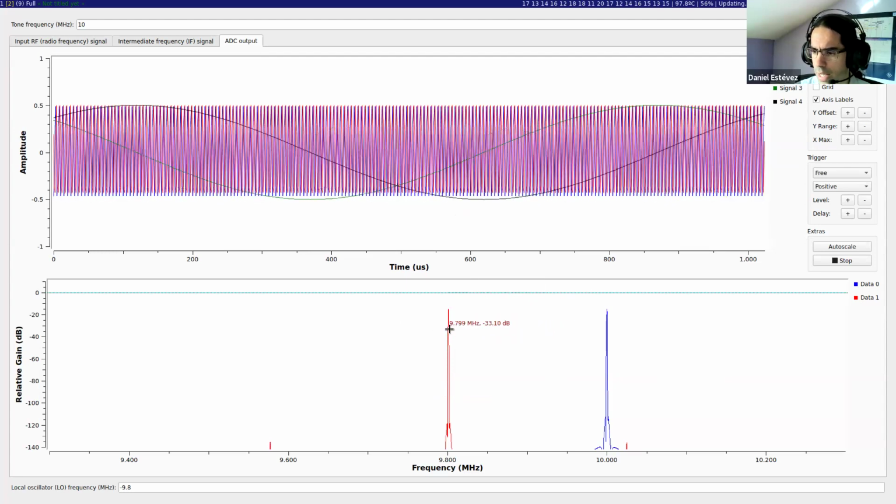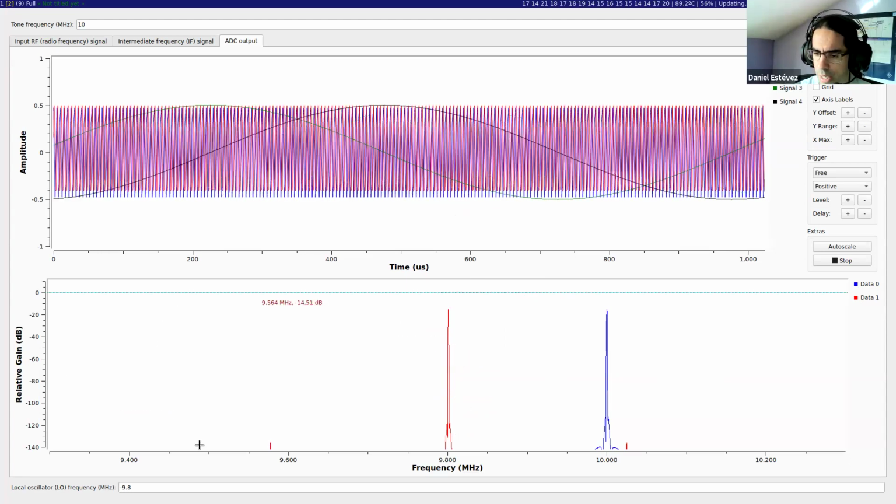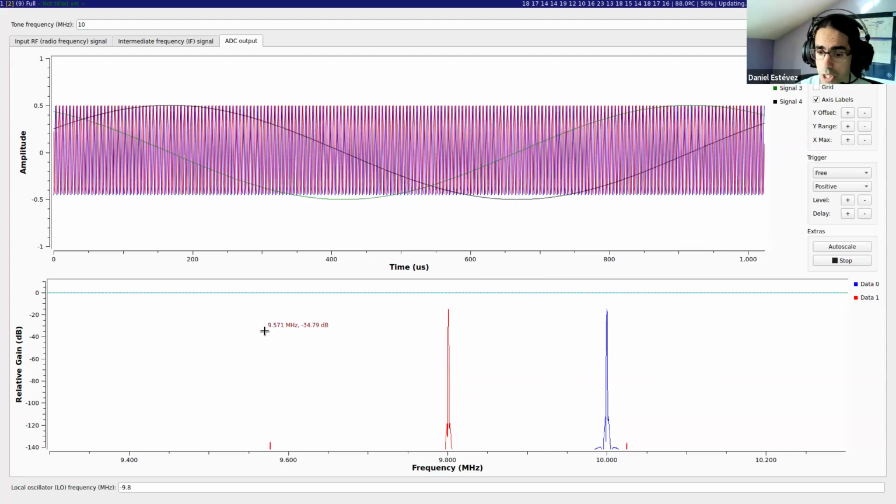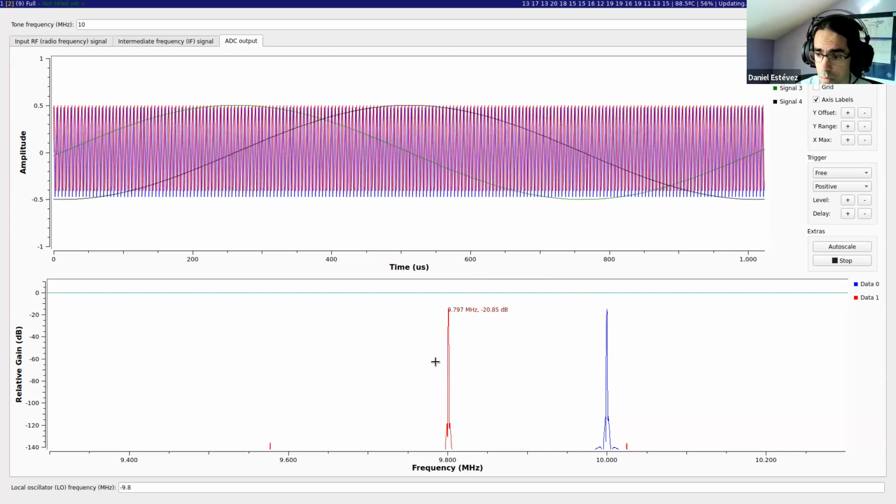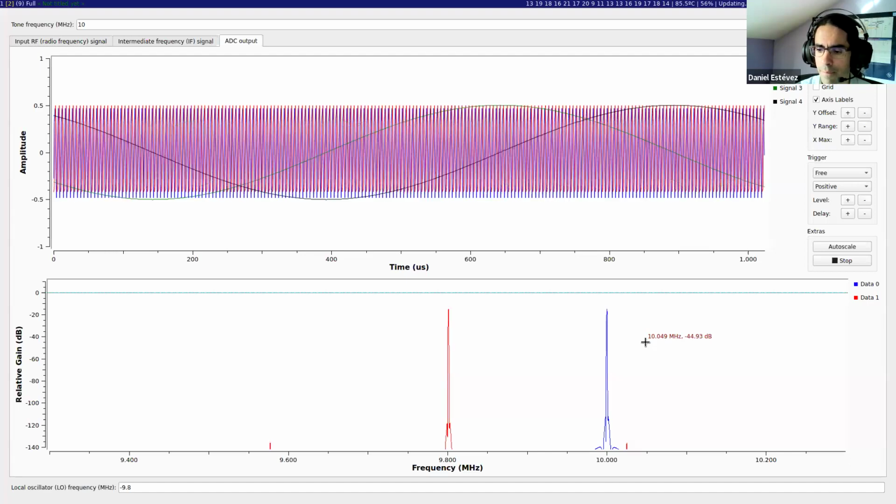So really the ability to tune to a center frequency and have some signals which are to the left of that frequency, which are negative frequencies with respect to the center, and signals to the right, which are positive with respect to the center, is the advantage of complex signals. Questions about this?